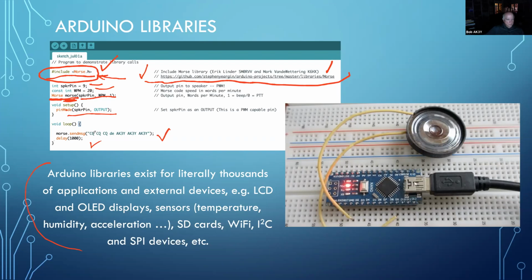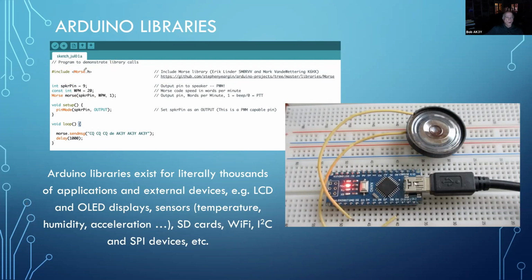So again, a couple things to be looked for. One is you want to look for a library which can do a lot of the functions you call. This makes the Arduino extremely powerful. If you look at the ATmega328P microcontroller really carefully, it's not a really powerful machine. It does certain things very well, but it's not powerful at all. It's not going to do real-time FFTs, for example. We'll talk about how you can do that a little bit later with a souped-up version of it. But it's not going to do a lot of signal processing for you. It's basically a controller.